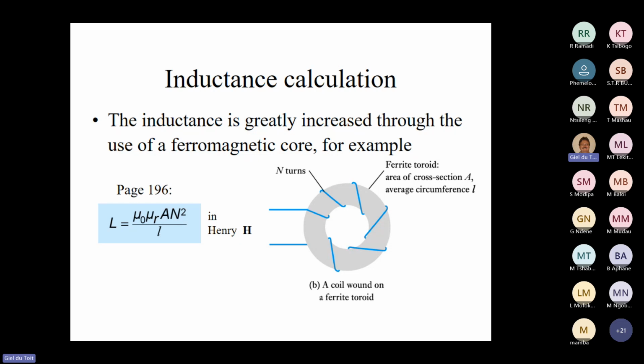So the length of the inductor is the length of this core in length. If this core was a straight core, in other words, a piece of iron that was just long and straight, like 10 centimeters long, like a rod, then the length would be, in that case, 10 centimeters, which is 0.1 meters. Always work this length in meters.